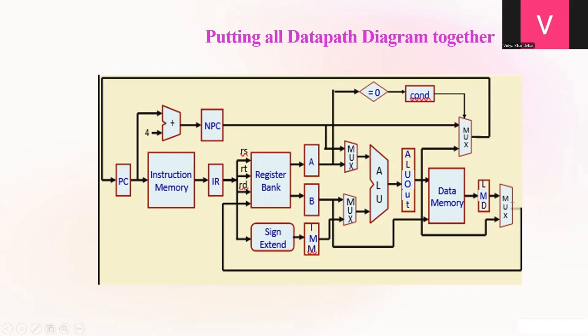Initially the PC hits the instruction memory, and the instruction is read and stored in IR. After it is stored in IR, the instruction needs to be decoded. At the same time, when it gets decoded, some of the other registers get populated: that is A, B, and immediate.